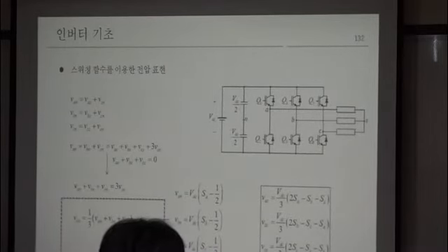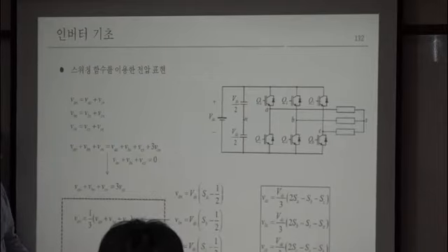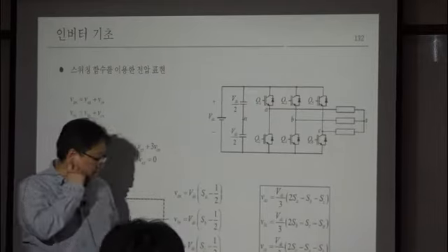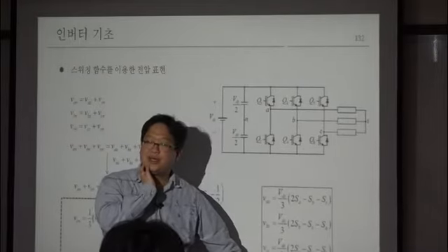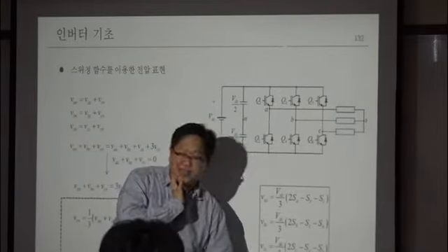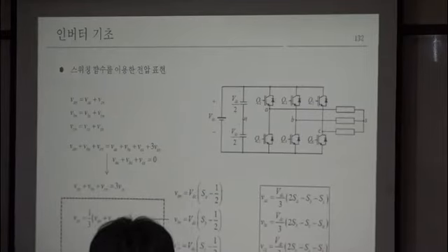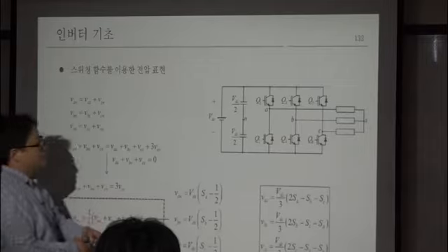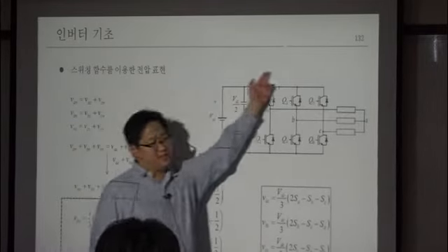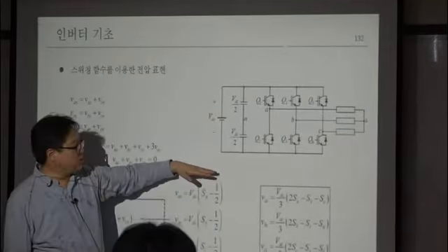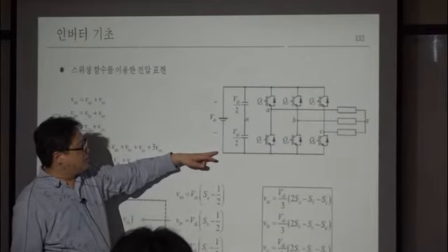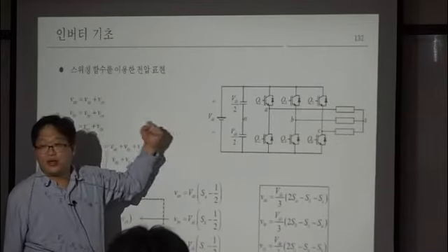So this VSN is pretty important. Physically, it creates an EMI source, and it also creates the leakage current in a three-phase inverter. How? Because this is a simple circuit, but in all circuits, where is the ground here?